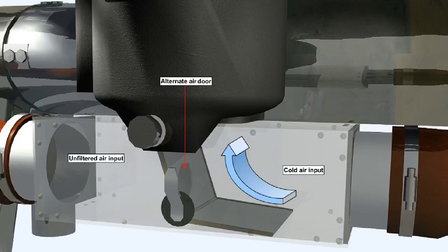It's generally accepted that the fuel injection units used on the engines used in most light aircraft do not need heated air for the purpose of induction venturi icing protection. However, it has been suggested that operators should consider incorporating an alternate air door as a means of preventing manifold air starvation caused by filter blockage from icing or other ingested materials.